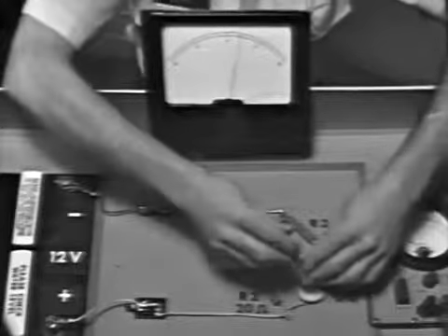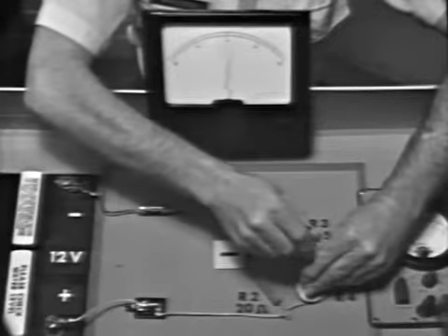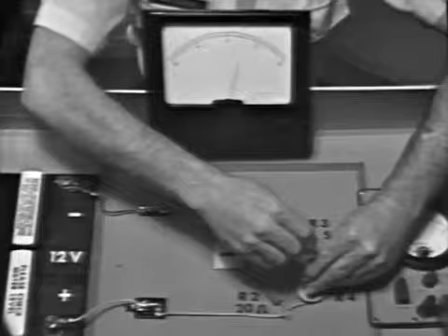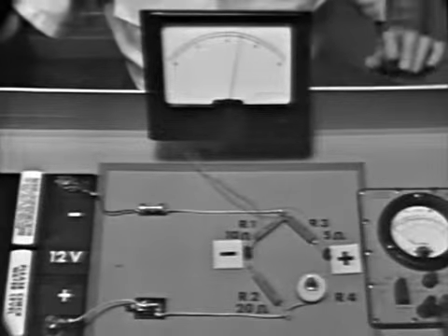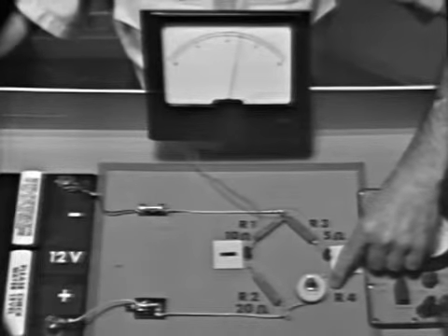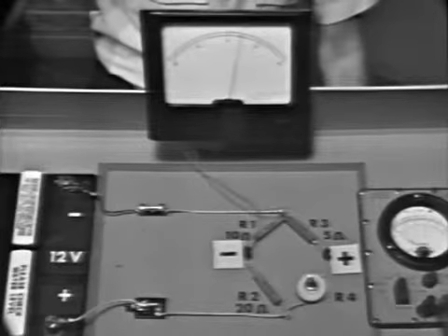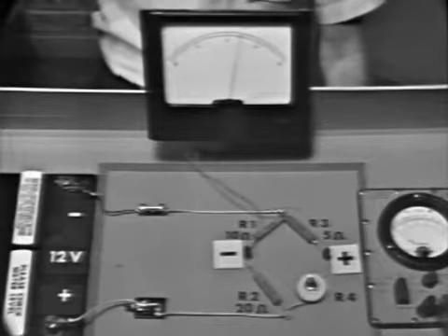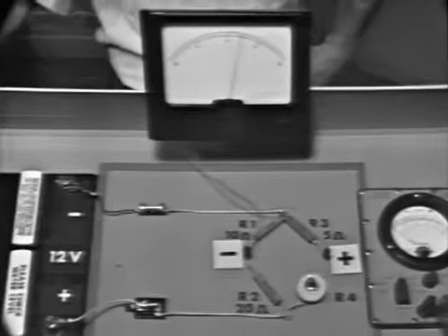So notice then that with a single control, this rheostat, we can cause current to flow in either direction across the bridge. And of course we can vary the amount simply by upsetting the ratios more. Now this feature of the bridge circuit makes it extremely valuable in applications such as weapons control systems, antenna positioning, measuring devices, and systems where a high sensitive control circuit is required.